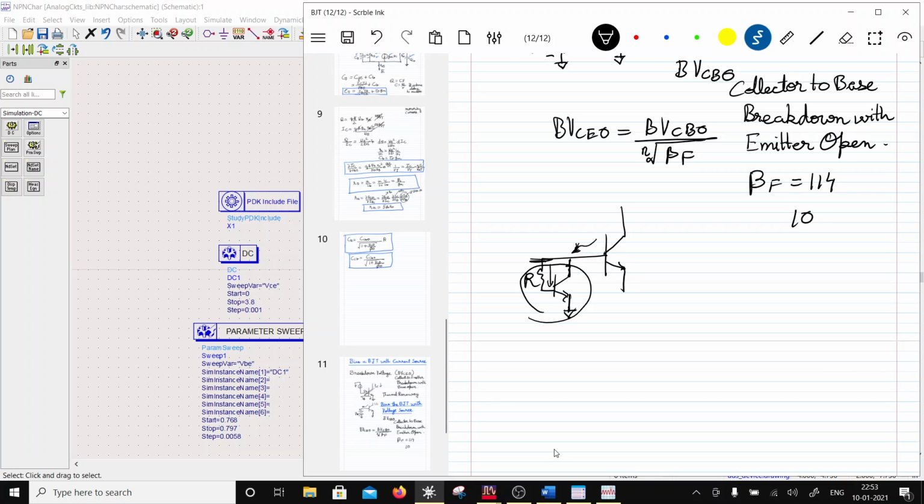So as soon as you start getting the negative current, you take that current and steer it in here. So the breakdown which you see here because of runaway is not going to occur, because the current is not forced to flow here, but takes the path through this transistor. So though biasing with the current gives you a more linear transistor, you have an arrangement to swamp all the negative current so that this breakdown can be shifted away.